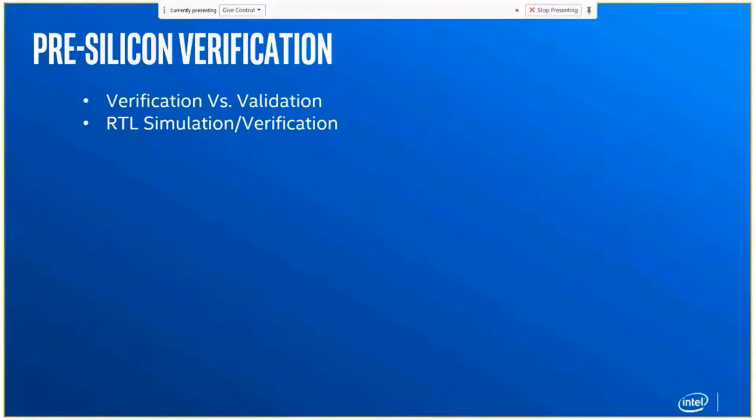It's again at the low level, right? So if you raise this clock, is it responding on the other end? If you put this value in this register, is it configuring that device correctly at that kind of level? Is that adequate to confirm that the chip is done and then ship it out? Absolutely not, right? Because you are way too down into the individual register level and you are definitely going to miss a lot of higher level functionality. So that's where several other verifications come in.